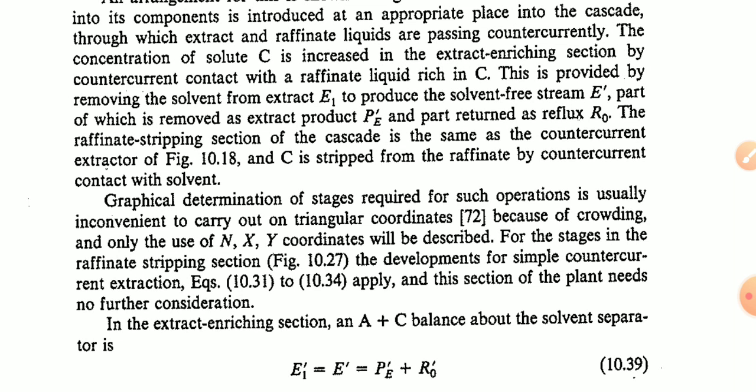Now, graphical determination of the stages required for such operations is usually inconvenient to carry out in triangular coordinates because of crowding, and only the use of an xy coordinate system will be described for the stagewise contact in the raffinate stripping section.